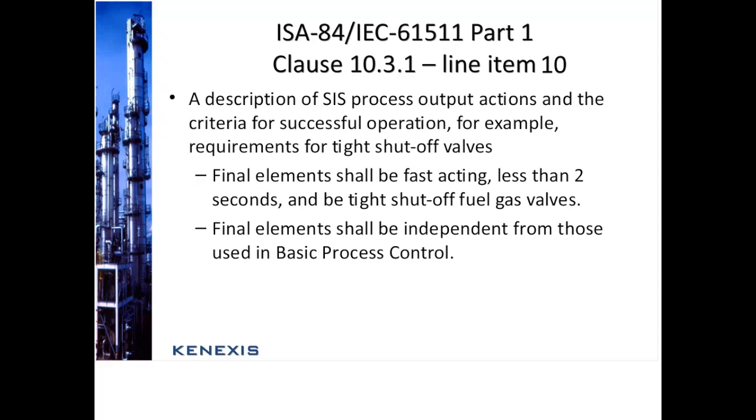So in your SRS report, in the definitions of your final elements, the documentation should follow something like this. Final elements shall be fast acting, less than 2 seconds, and be tight shutoff fuel gas valves. The final elements shall be independent from those used by the basic process control system.